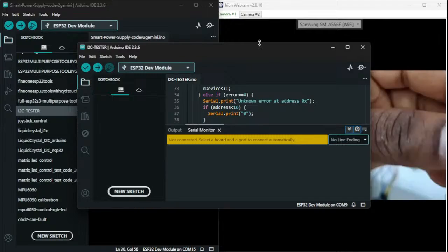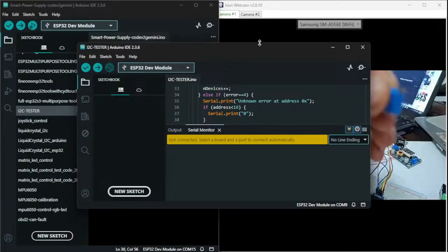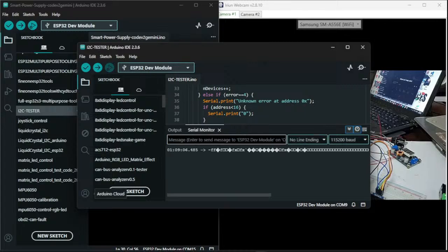So you can see this blue thing, that's the potentiometer that you turn, then the resistor in it will start changing your voltages. So now instead of using that, or any potentiometer that I know, which is around 5k ohms, I'm going to use my MCPs. But before I do that, I have to test them first.